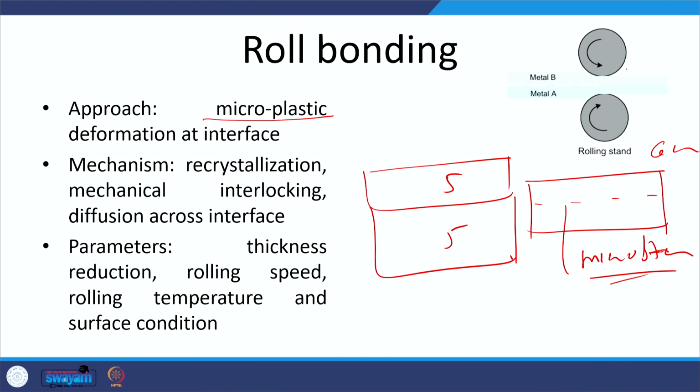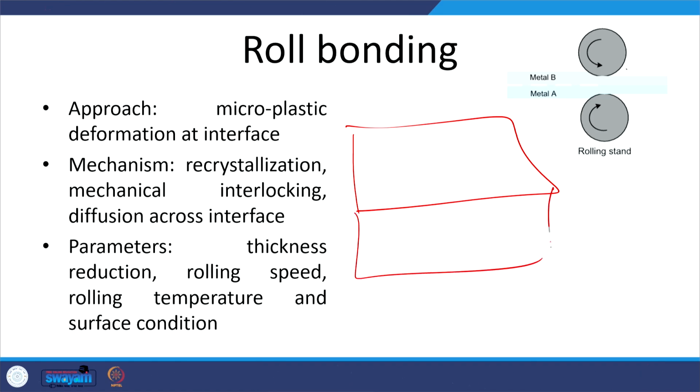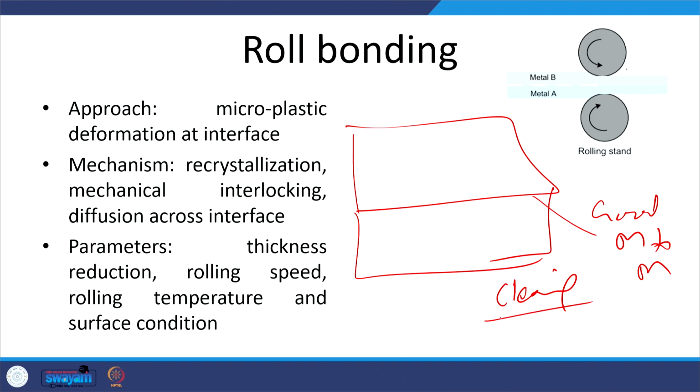So, what is important for this bonding? Okay, that is important to be seen. So, obviously, since we are just rolling the things by stacking the sheets together, there must be very good metal to metal contact between the 2 sheets, and for that what is necessary? Very good cleaning, free from impurities. Okay. So, surface roughness of the sheets coupled with the cleaning will ensure good metal to metal contact, especially when these are rolled.